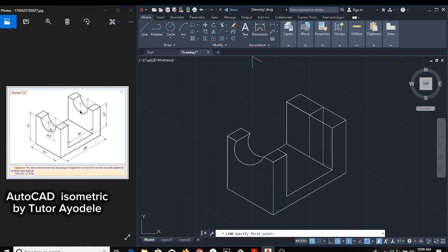That means from here to here is 15 as given as the radius. You can see the radius is 15. So we need to get here to here as 15, to tell us where our circle is going to extend to. So from that point, I'm going to go 15. Just enter the unit 15. So I'm going to cut it this way.